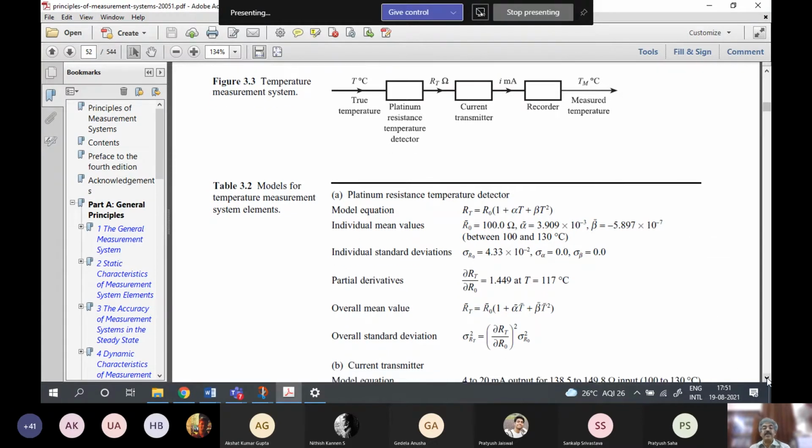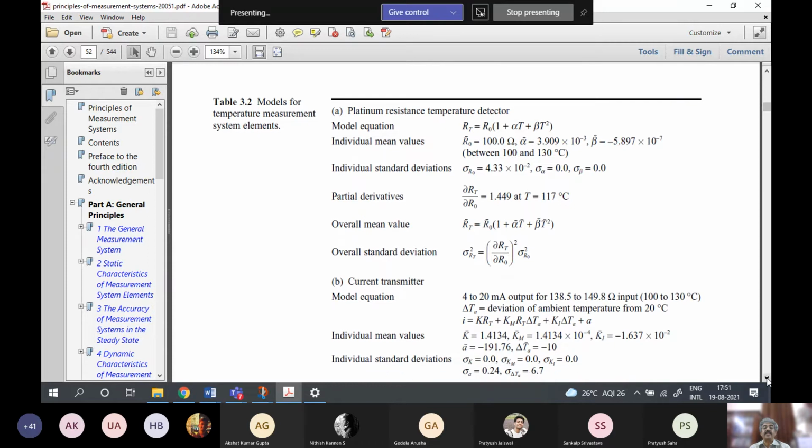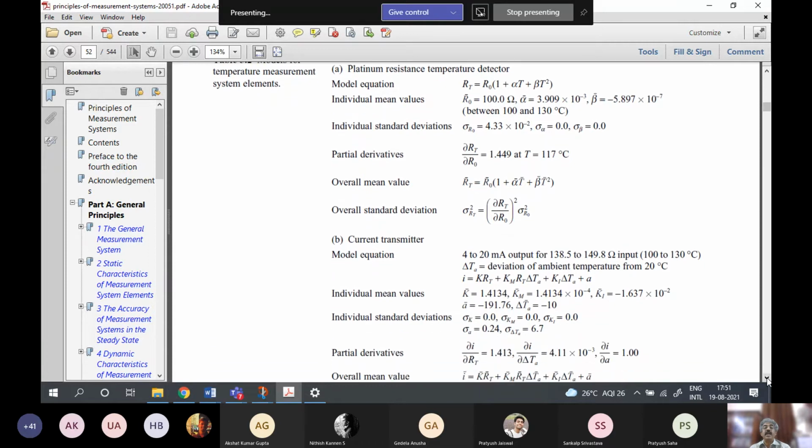So exactly the same thing. So this is what they are doing. So see, the platinum resistance value changes with temperature in a nonlinear fashion, and that is always true, although we learned in our first year only the first 2 terms. But when the temperature is high, the difference is high, then the term beta comes into play. Again, beta is small, as you can see.